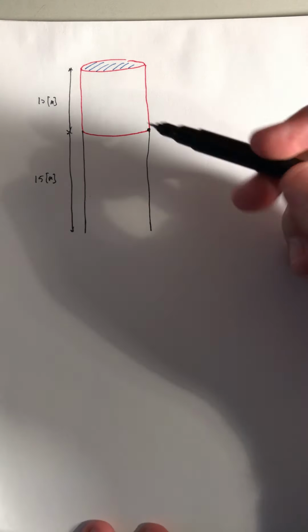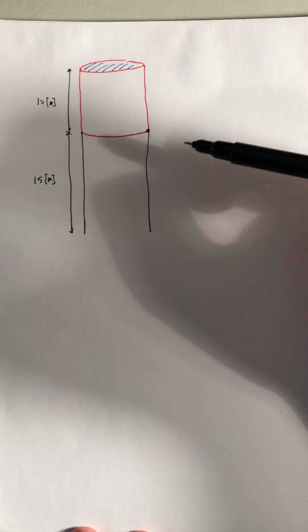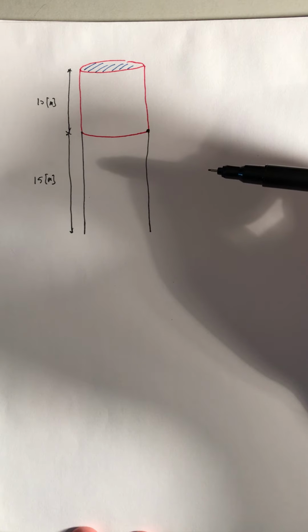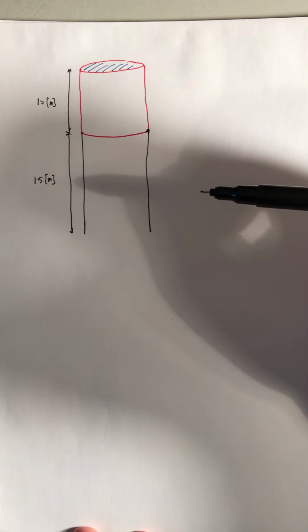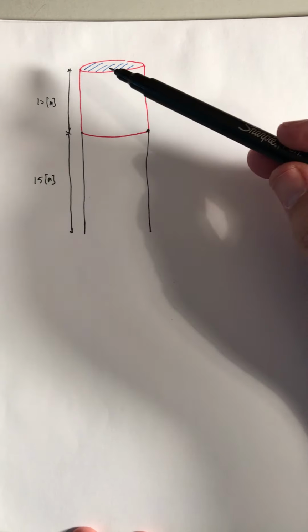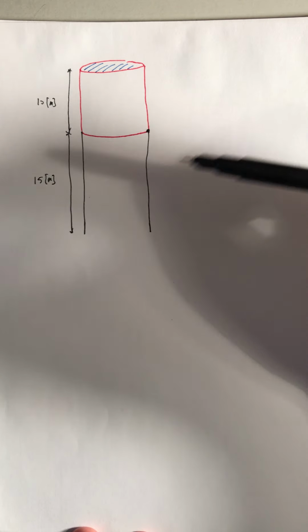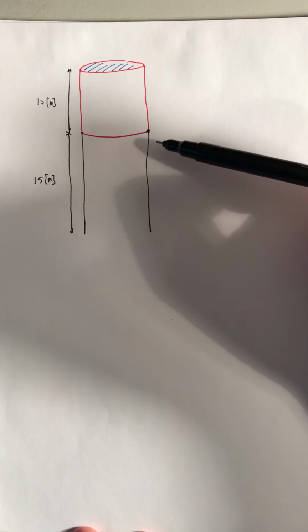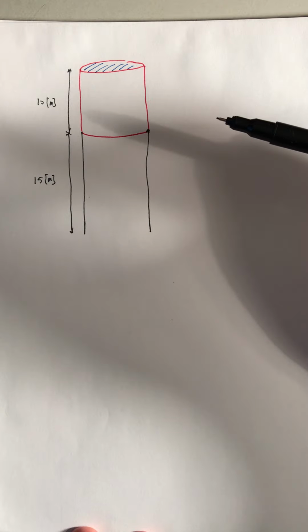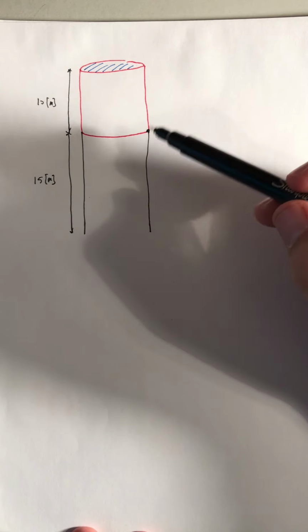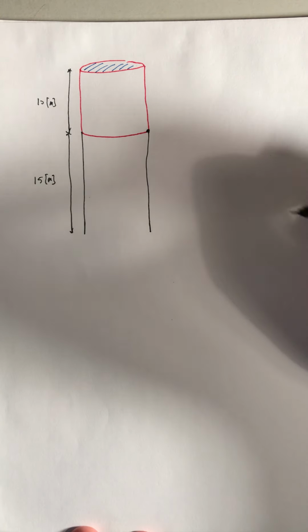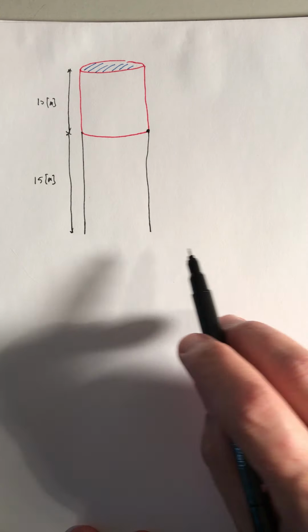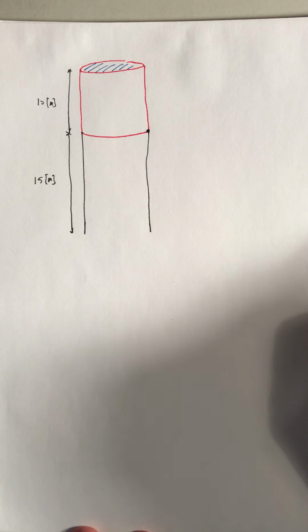I have an example using Bernoulli's principle, which is conservation of energy during the flow of a fluid and a relationship that holds along a streamline. We have a water tower open at the top, and unfortunately it has a hole that's developed in the bottom. And our task is to determine, as that hole is opened up, where along the ground is the water going to land at first.